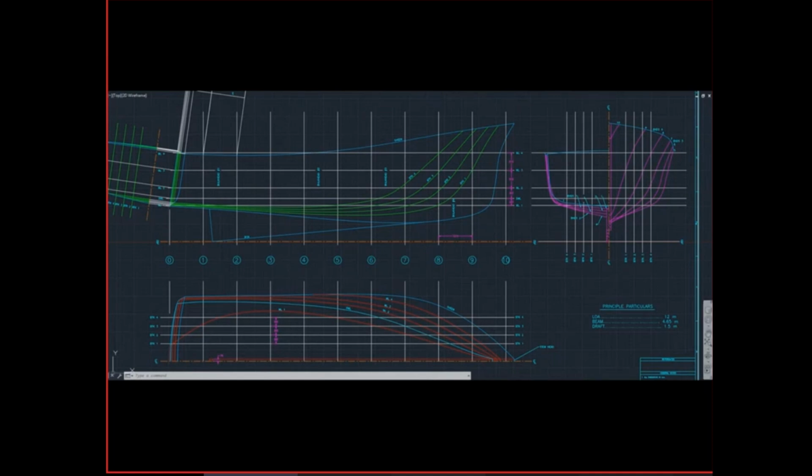Now, in the profile view, you also see these horizontal straight lines, and these horizontal straight lines are water lines. Of big importance is something called the design WL, or design water line. This is where the vessel is expected to float when she is loaded as per standard and when she's in calm water.